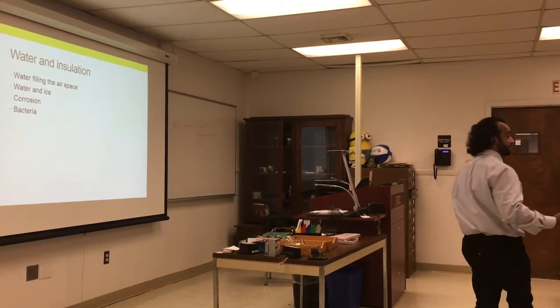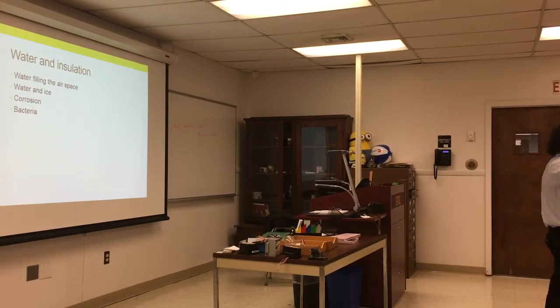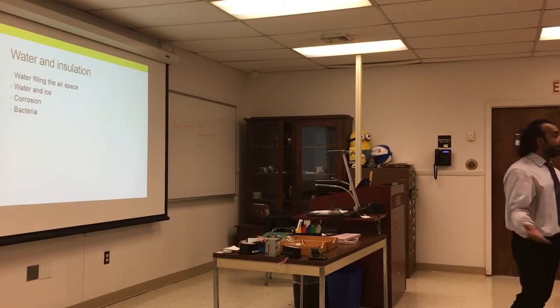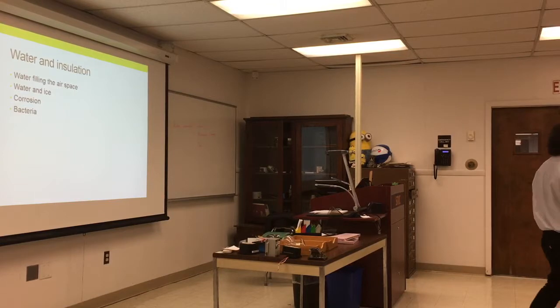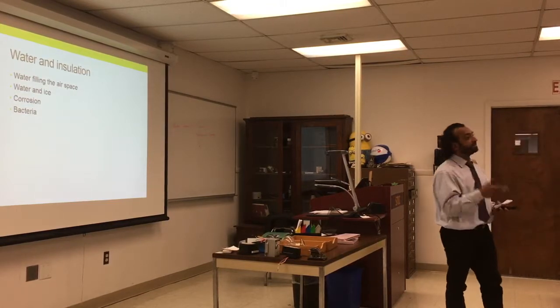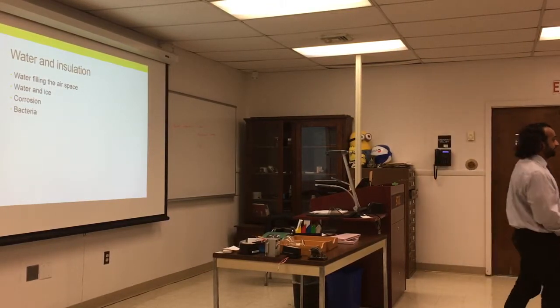If you don't have a gutter, you have just a roof. The water will seep into your walls and go through the cement into your basement. So by law, you have to terminate at least 3 feet from the house. Make gutters a little bit slanted so the water will go away. Otherwise, you will always have water in your walls and basement, and you increase the humidity. Those sort of things make a difference.